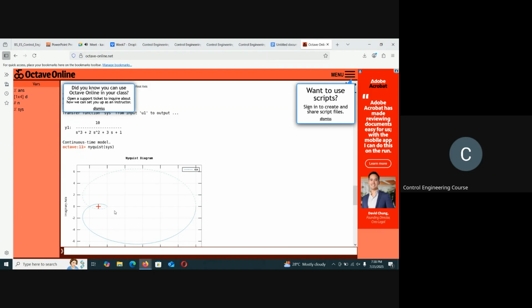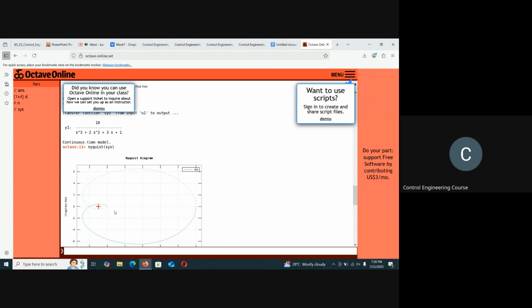Okay, so lots of such subtle things are there. In that case, the Bode plot gives you the information about the zeros as well, that you'll see in the Bode plot design. So you have to start playing around yourself so that you are getting comfortable with visualizing Nyquist, Bode, and root locus, both intuitively and using MATLAB for precise design. Is this clear?